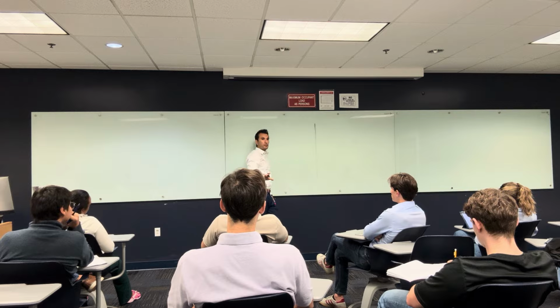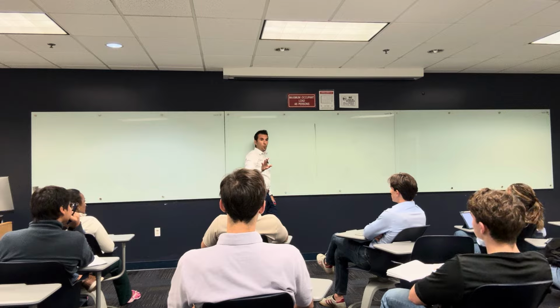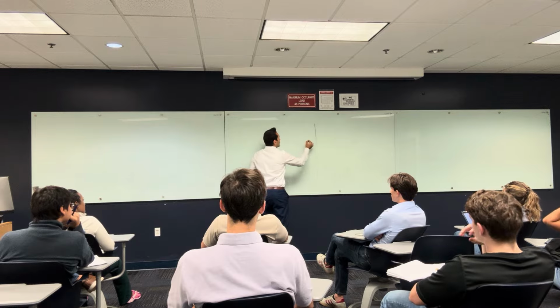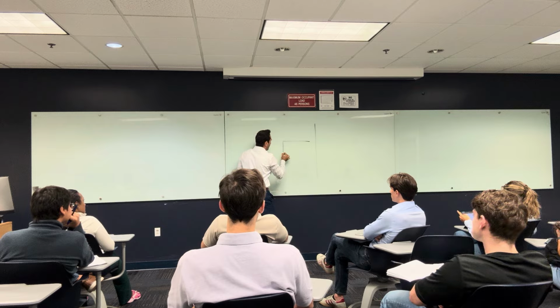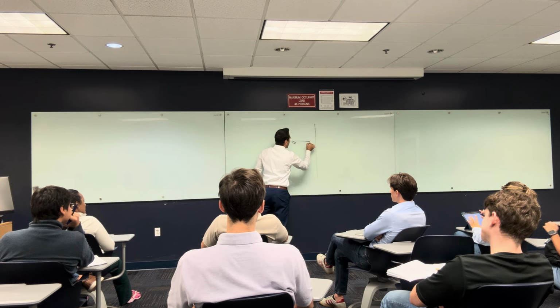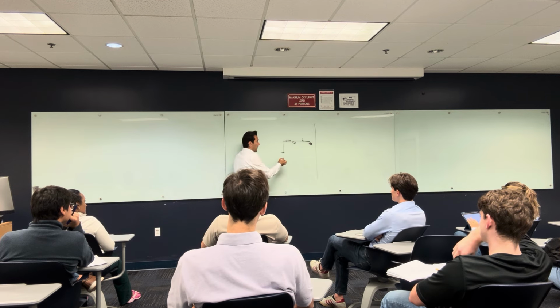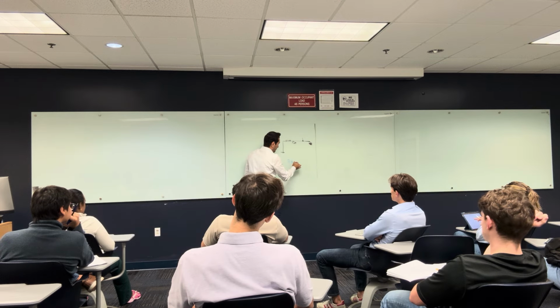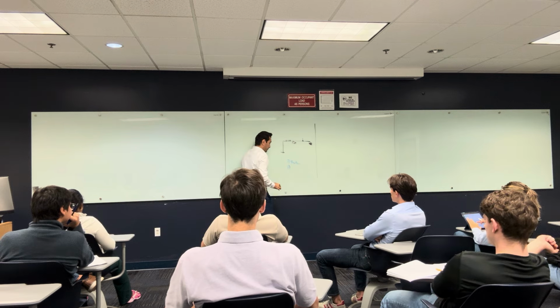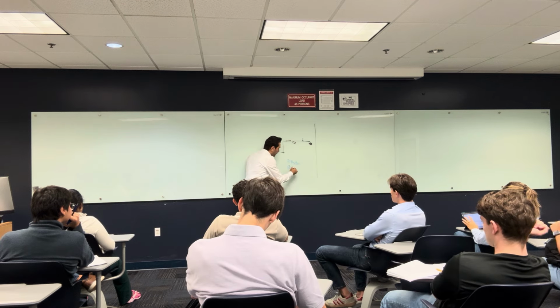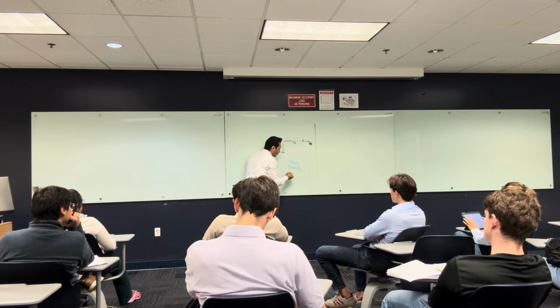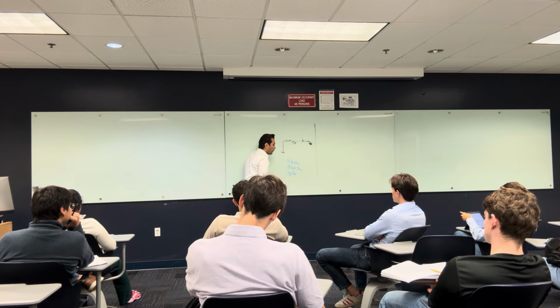As structural engineers doing structural analysis, what do we want the analysis to generate for us? Let's say you have a frame like this, with a bunch of loads, and you are gonna do structural analysis. We discussed this before. Structural analysis is gonna give us what? Counter forces. Reactions. What else? Internal forces, excellent. What else? Displacement, strain, deformations, because internal forces can be transformed into stresses.